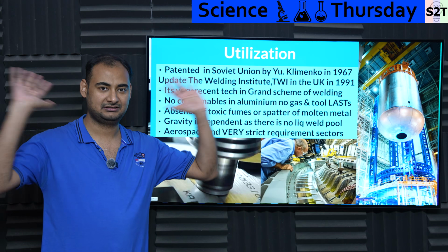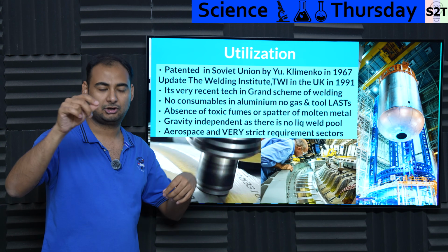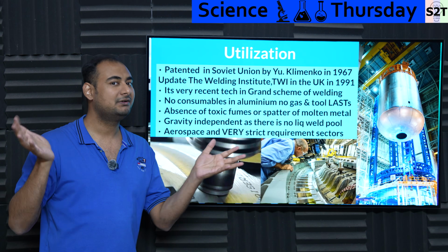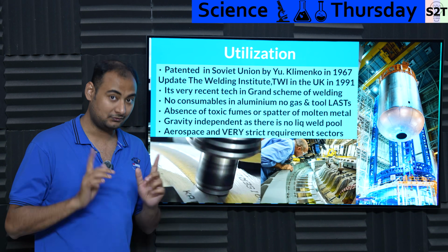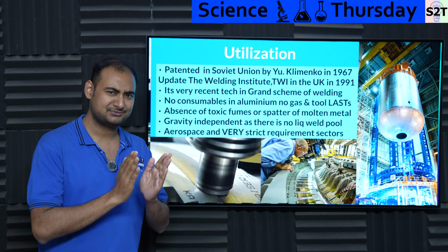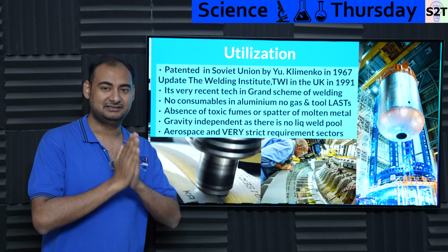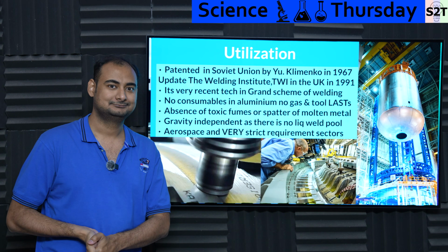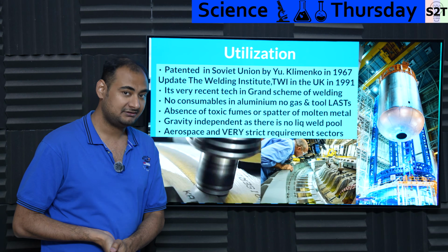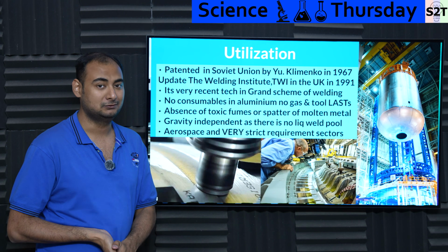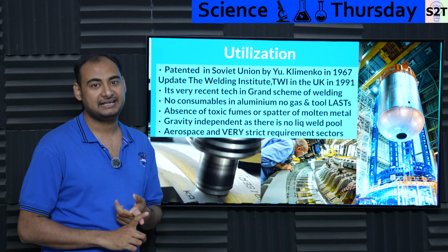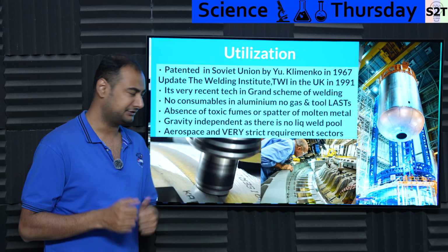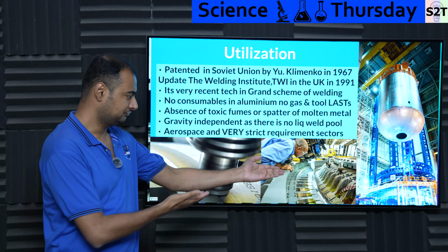Let's just say you are in a welding shop and the pressure regulator broke, or it slowly started to leak argon. Argon over time will displace every gas in the room, and you only have a very small amount of oxygen left. Displacement will cause an asphyxiation hazard and kaput. Trust me, people have passed away with that. That's how we know. So not having any gas, great. Not having any laser scatter risk, ultra great. Not having any fumes, GG.